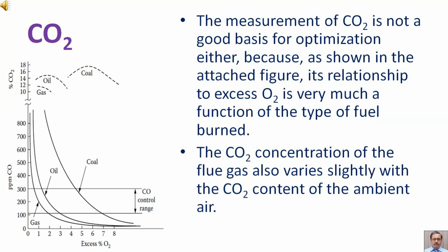The measurement of carbon dioxide is not a good basis for optimization either because, as shown in the attached figure, its relationship to excess oxygen is very much a function of the type of fuel burned. The CO2 concentration of the flue gas also varies slightly with the carbon dioxide content of the ambient air.